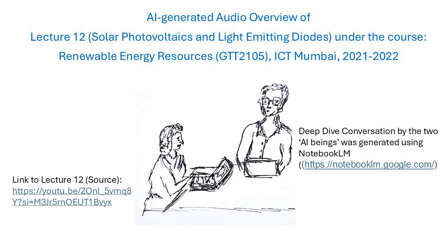You connect them together to get more voltage. You wire cells in series, positive one to negative of the next, and so on. Like batteries in a flashlight. Exactly. So a typical 12-volt panel might have, say, 36 cells in series. Each makes maybe half a volt, but together they produce maybe 17-volt open circuit, enough to charge a 12-volt battery nicely.